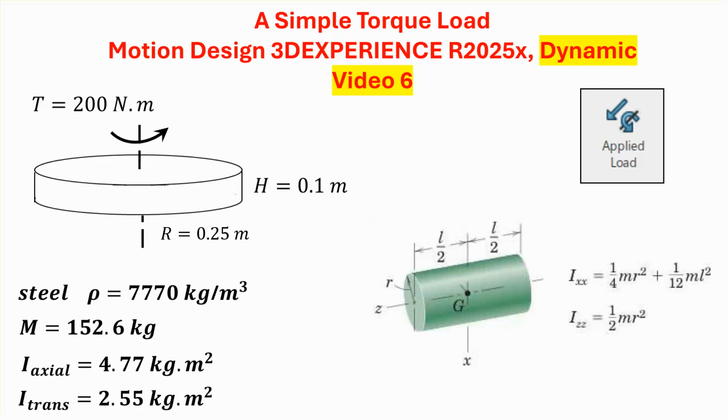Now, when you're dealing with torque problems, one of the things that you have to calculate when it comes to hand calculation is basically the moment of inertia about the axis of rotation, which is called I-axial. And if you go to a strength of material book, you will see that this I_z, 1/2 m r squared, is given explicitly. You also have moment of inertia about the other two directions, which are called transverse directions, but in a pure torque problem like that, it doesn't come into the picture. But anyway, let's move on. The simulation is going to be done over 10 seconds.